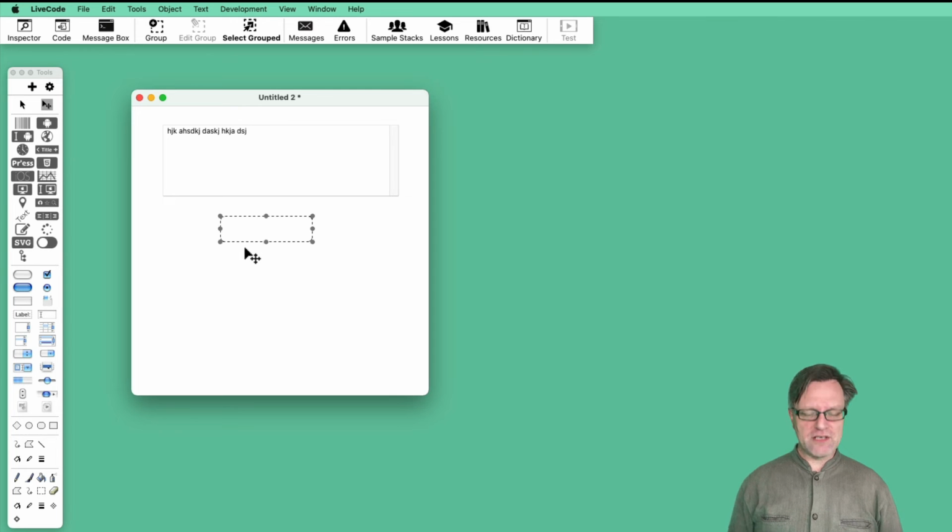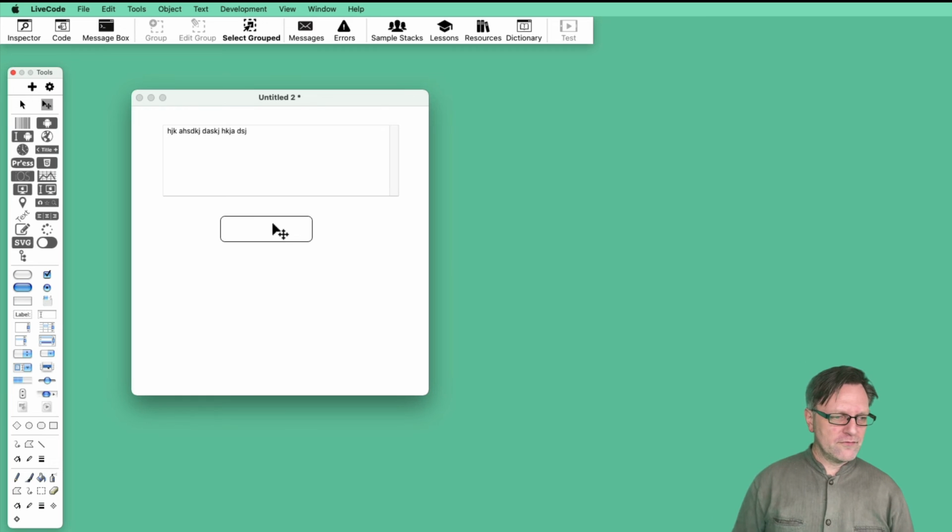Therefore, I use these a lot, these 4 items here. Because if you like to have some kind of backdrop, well, then you can add, these are called graphics. Then you add a graphic, and then you can set the background color. The next part is also about graphics. So here you can set the graphic fill color, you can set the pen color, and you can set the graphic line size, and then you can take this one to draw something.